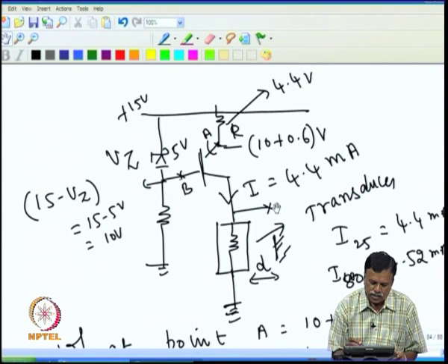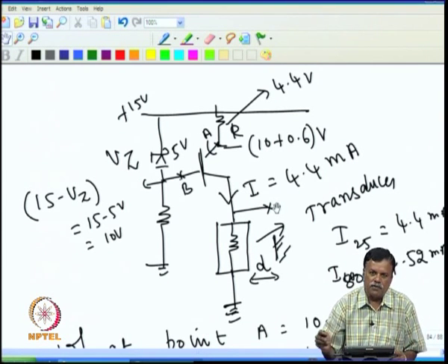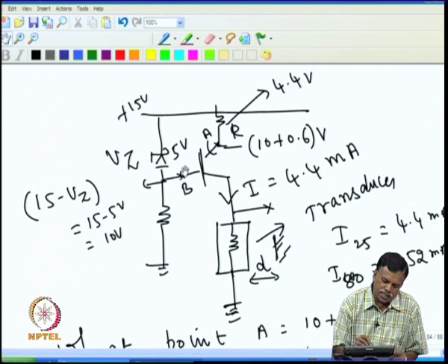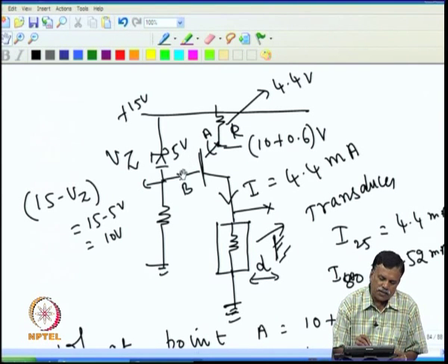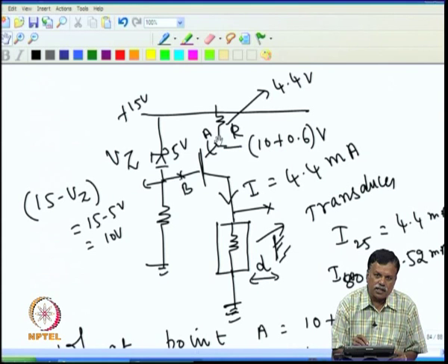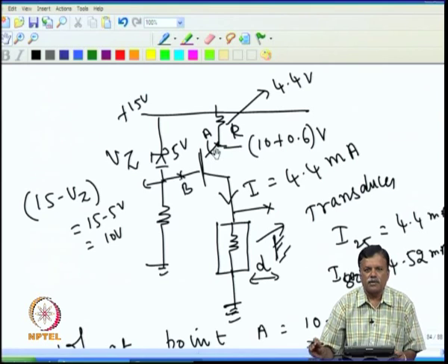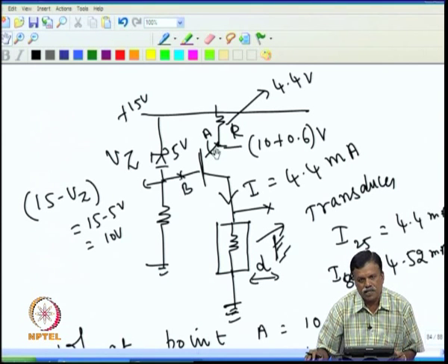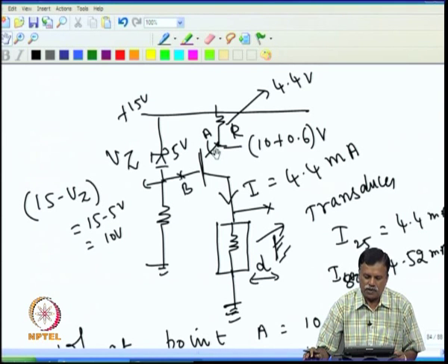So, this is another use of the transistor, that is we can use the base emitter voltage change. The base emitter voltage changes with the temperature, and that can be used to our positive advantage to compensate the temperature change of the transducer and so on. These are very important applications. Actually we have constructed a constant current source whose current is not really constant, whose current is really changing with temperature, and that change was used here as an advantage in this circuit.